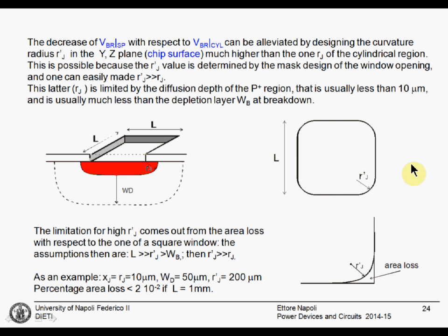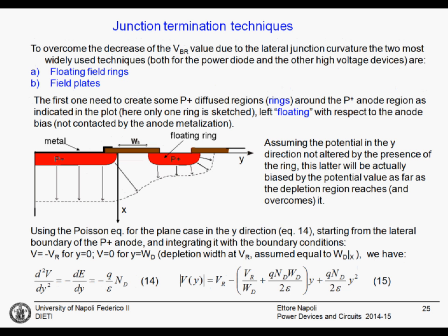The first point is then solved. Just make rounded corners. For a very small chip in some low power or integrated application, you can also see round power devices. A diode that is just a circular layout. It is the extreme case of rounded corners. And this solves the first problem.